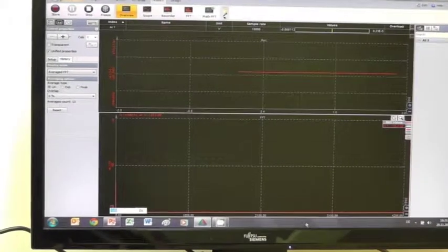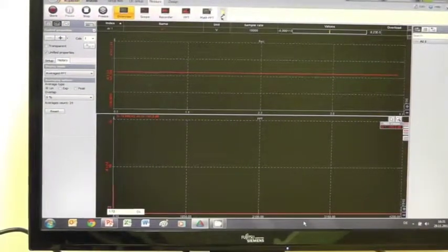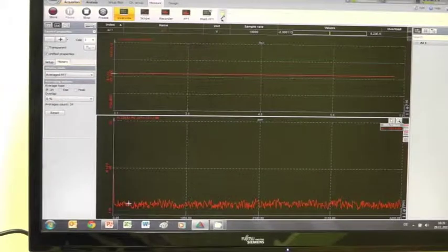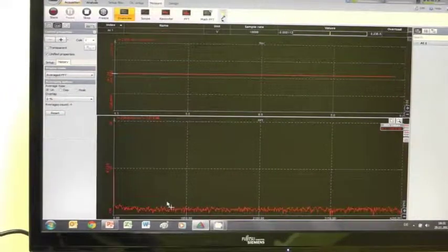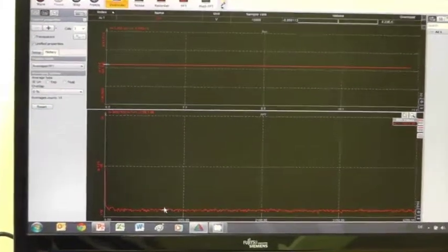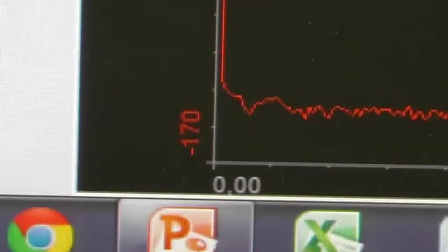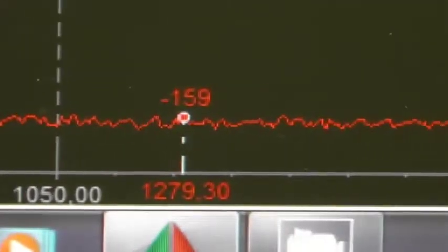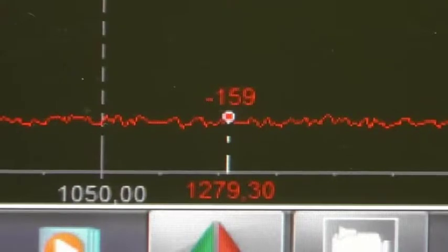Now you see the scaling is minus 140, you can't even see that anymore. I go to minus 170, press reset once, and then we can see up to 160 dB dynamic range. This is what we see here in our newest dual range, dual core application.